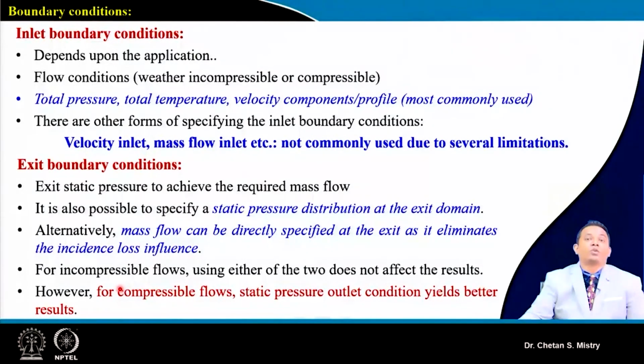Okay, and that too you need to put in an interval, because just understand your computer is not understanding your code. It will get a setup of calculation of different parameters, and that will be helpful to you in order to capture the shocks. So there is a technique for that, in which at certain intervals, after a few iterations, people are changing the static pressure at the outlet, and that's how they are getting what we are looking for in terms of solution to the problem.